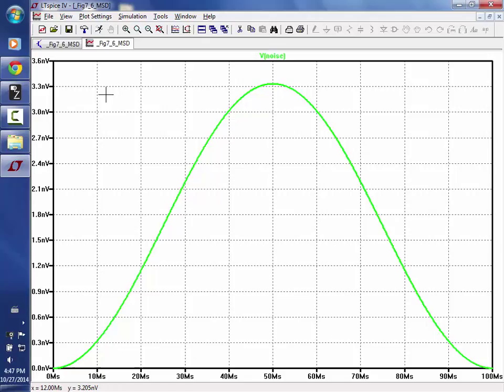Okay, so let's talk about estimating the RMS modulation noise. So this is 2.37. And I'm going to do this in 2 different ways. What I'm going to do here is assume a bandwidth B, and then calculate the noise in the bandwidth B, assuming a brick wall filter. So the filter comes over, comes down, boom, no sinc filter. Then I'm going to go through and do it with a sinc filter. If you look at those scripts, there's actually code in there to implement sinc filters if you want to see what it would be like if you were doing that in a real circuit. So does everybody follow that? Just a bandwidth B and then brick wall.